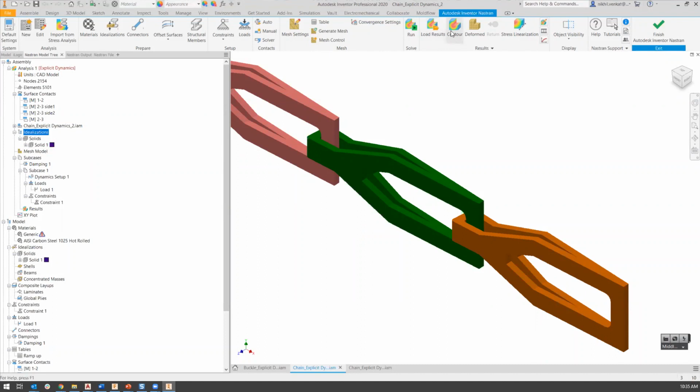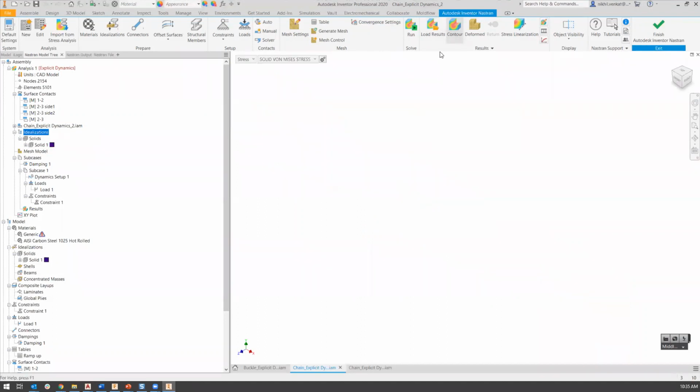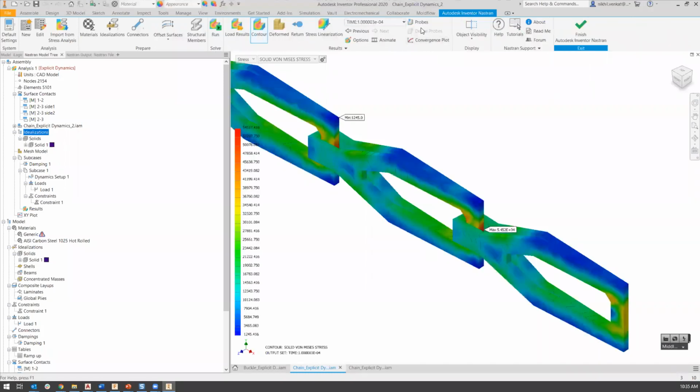Yep, and that was element specific, which brings it back to your mesh. Your mesh, exactly. If your mesh isn't fine enough, it's going to get rid of these huge elements, and it's going to look super funky. Yep. So the more refined your mesh is at those areas of interest, where those high points of stress are, the more accurate your model is going to look if it starts removing elements. Because you're going to get some weird jagged edges and stuff. It's like, why did it remove this whole element?